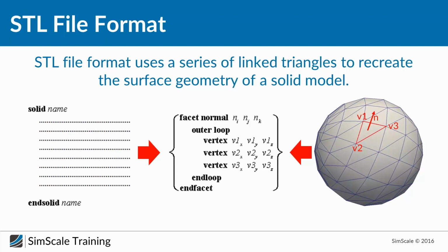If you write out a single STL file, that's what Akram was talking about when he said you lose topological information. An STL file cannot differentiate whether it's a solid, a face, or even just a part of a face. And our concept, also for model maintenance later on, is that you make an assembly of all the parts you need of the car, like the front wing main plane, end plate, etc. Then you export every part as its own STL. And before you upload them, you merge all files together. I will show you later how this can look when I present the homework to you.